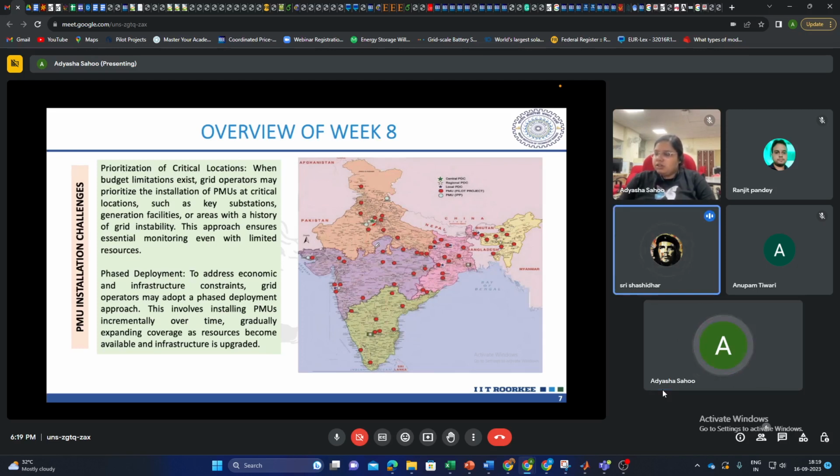So are you trying to say the same thing? I was not sure how they will have the data. Through the communication link itself, we will send the data to them. They will have the status of each of our isolators, breakers, and whether the line has tripped or not. Even the current flow and the power flow, they will get every data through the communication link. We have two communication links for redundancy too.